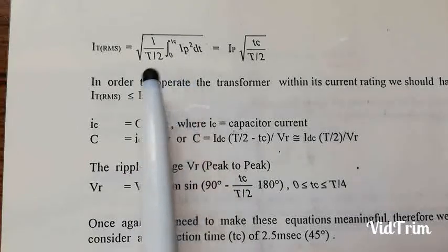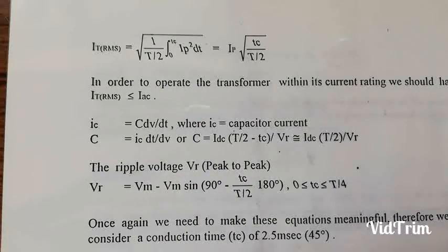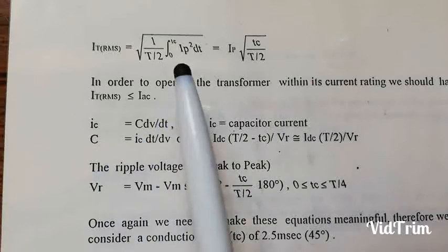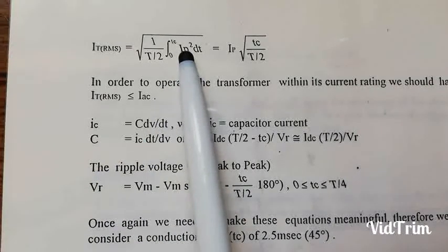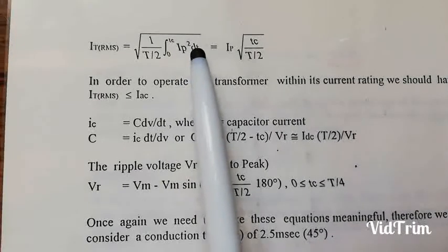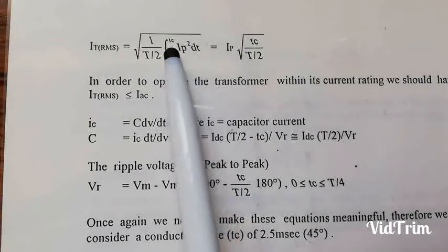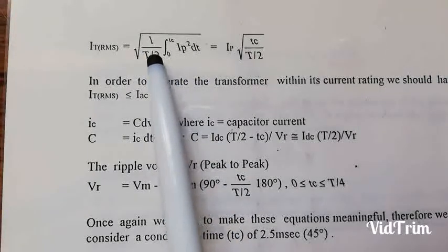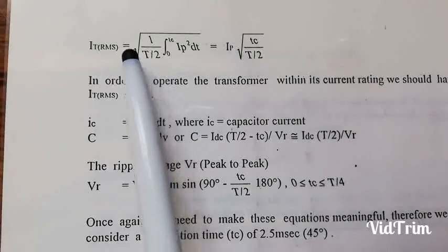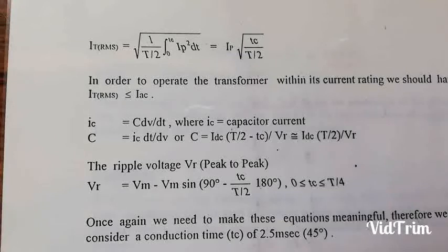Okay, we'll convert it to its RMS value. To convert something into its RMS value, you get the value of it, you square it, okay, then you find the area, which is multiplied by the time, the dt, and you find the whole area by integrating that, and after that you average it over T over 2, because that's half of the period, and after that you take the square root. So this is the rule to find the RMS for any given signal.